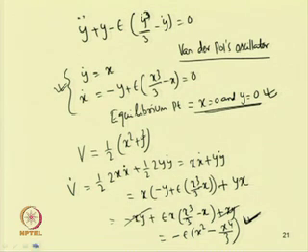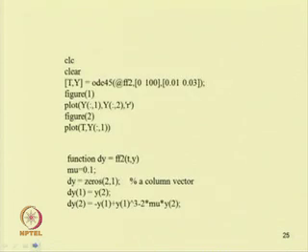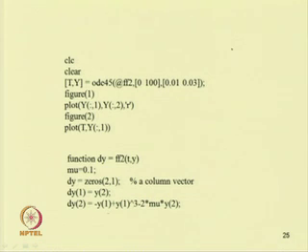So, let us see, to obtain the solution one can use numerical techniques. Using MATLAB also one can find the response of the system. For example, in case of this Duffing equation, one can write this program using ODE45. For ODE45 one can use the simple commands.